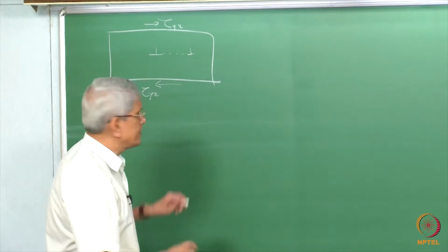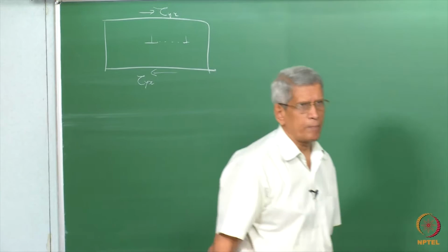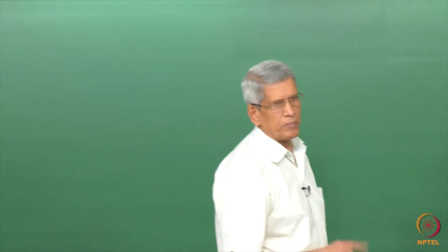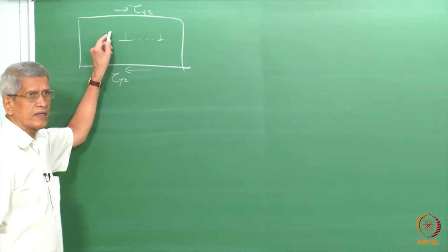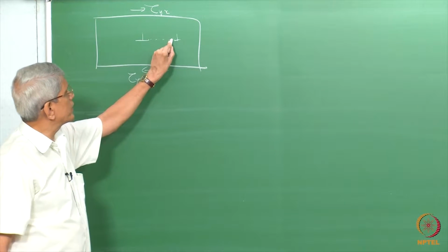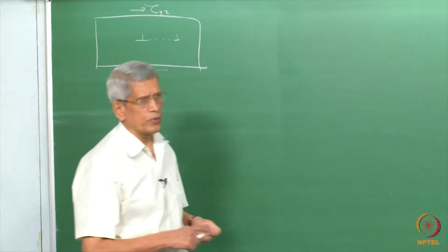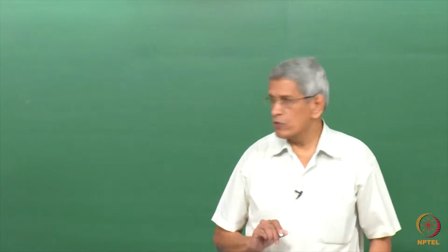So as a function of the position of the dislocation in the sample, the self energy remains the same, it does not vary. The only thing the external stress does is make the dislocation move from one region to another. It is equivalent to a unit length of a dislocation.